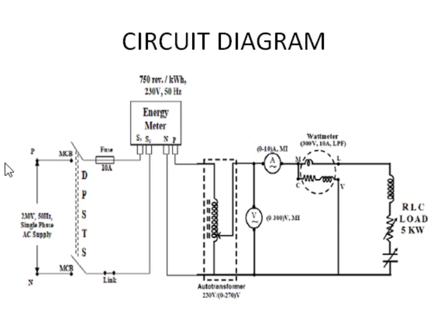This is the circuit diagram: phase and neutral, a single phase 230 volt, 50 hertz AC supply. Through the MCB and fuse we connect a single phase energy meter. The single phase energy meter has 4 terminals. The first 2 terminals are the input, and the other 2 terminals are the output. In the input, the first point is the phase line and the other is the neutral line. On the output side, this one is the phase output and this one is the neutral output.